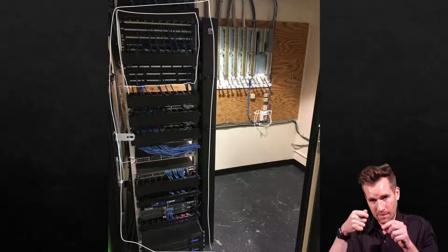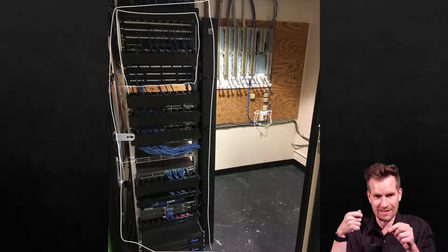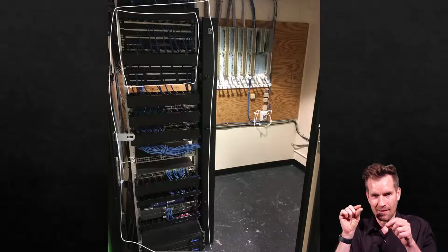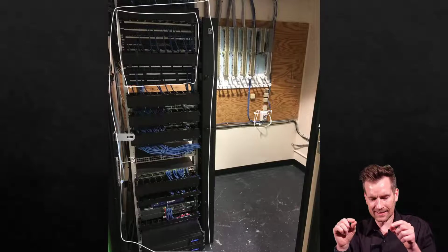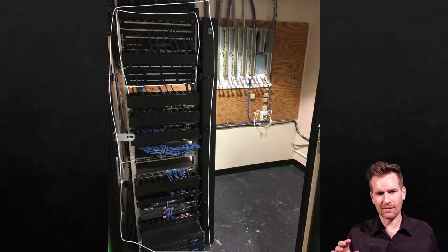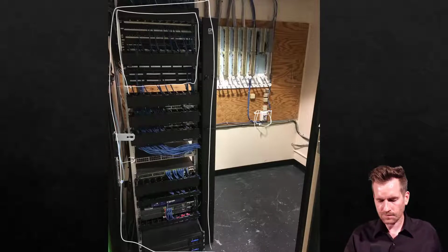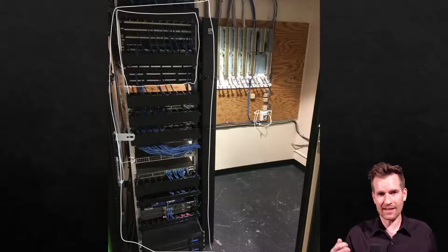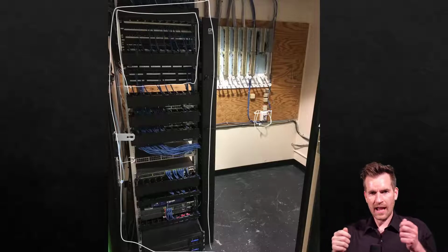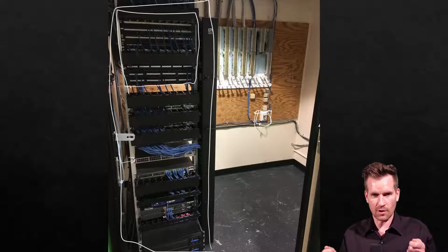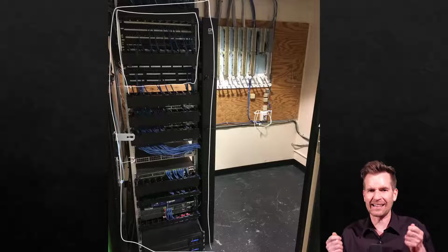There's a tool that actually punches it and pushes the little conductors into these little slots on the back. Later on I'll have a video about that. They connect onto the back here, and then on the front, I can plug in using an RJ45. And so I buy patch cables. I don't make patch cables. I've seen a lot of lousy patch cables, and it takes up a lot of time.